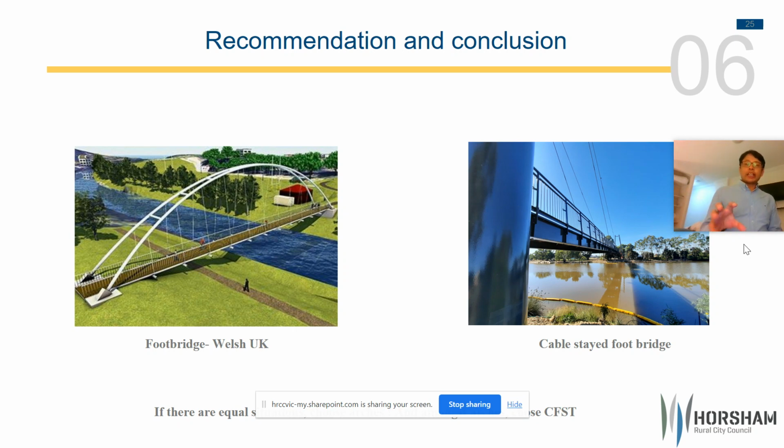in the cable-stayed or suspension type of bridges, all the loads are taken by those cables. Think about the connection point, the cables coming there and holding on to the deck. Those continuous movements, rattling of the steel, and how many fatigue problems there are. And we're talking about a life of 20 years or 50 years. And think of the problem: how many times would you change the cables, and how strong the material has to be.